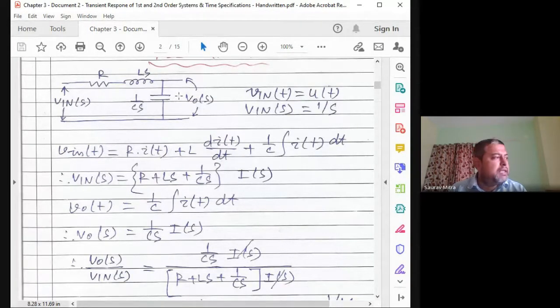Now, whenever you are finding a steady state error, first you have to see that you have taken enough time so that the output reaches steady state. You cannot measure steady state error when the waveform is in transient. Initially we found that the waveform is doing some kind of oscillation. There you cannot find the output response.